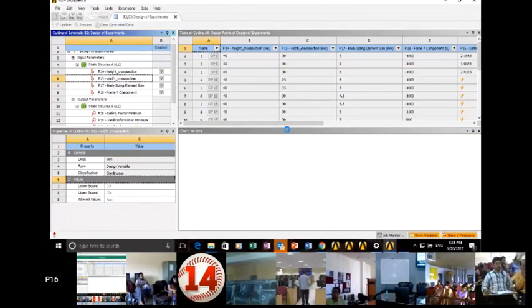In response surface studies, the software is building a mathematical submodel that describes the relationship between your input parameters and the output you have obtained. It will also differentiate the algorithms to model the response surface to capture linear and non-linear effects.